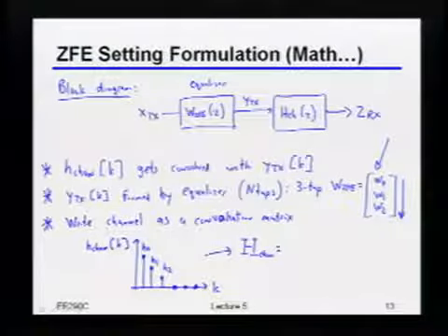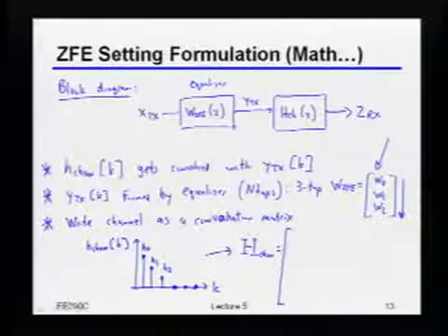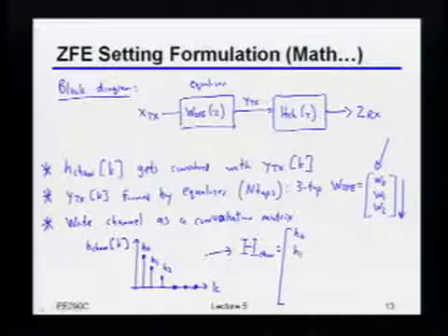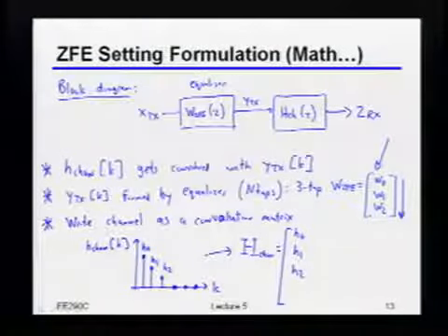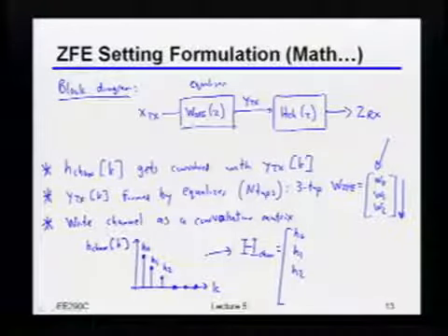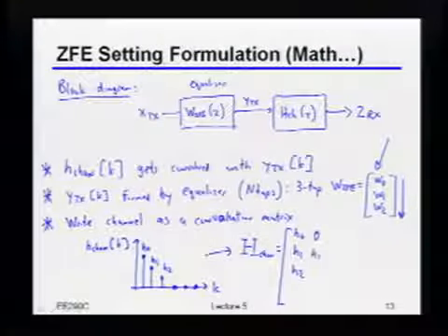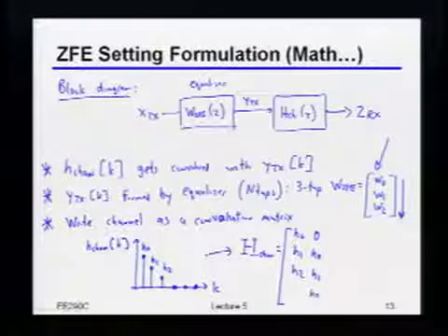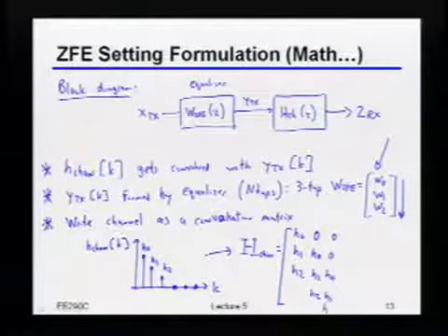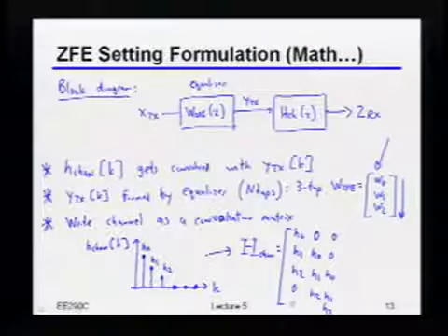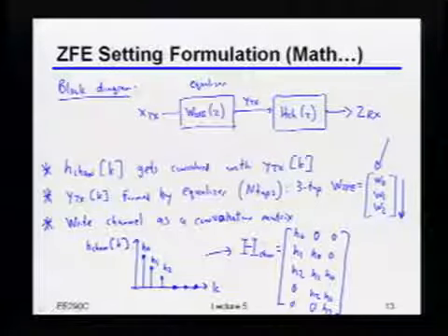And just to give you an idea of what that looks like in this specific example, what I'm basically doing is taking the channel response. But since I'm doing this convolution, I have to shift it by 1 position each time. Okay? So as an example, for the next bit position, I have to do that. Okay, then for the next one, I have to do that. Okay, and then if I fill in the zeros in the places that are left, I end up with something that looks like this. Okay?